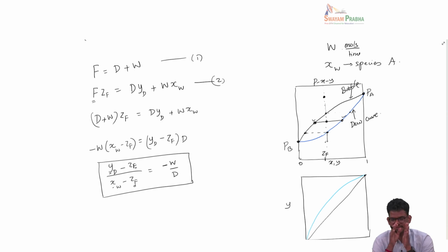Okay. So this was amply discussed in the last 2-3 classes. So again, you have to pay attention to this. This is a very, very important concept to understand conceptually. So what I'm trying to say here is that you have an option to choose a pressure in this range so that you will have a two-phase mixture. Above or below this window, you are either in the liquid phase or in the vapor phase. The distillation can happen only between these two pressures.